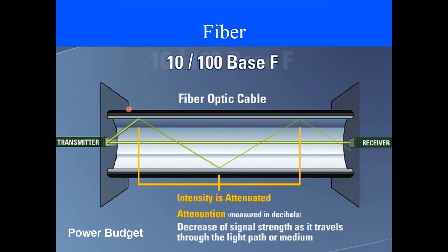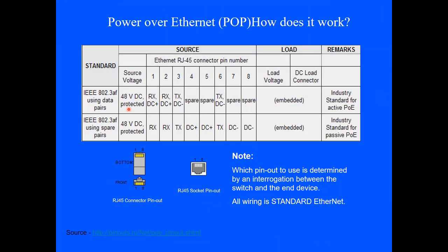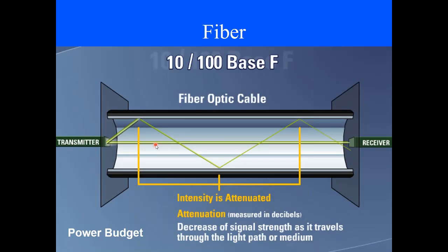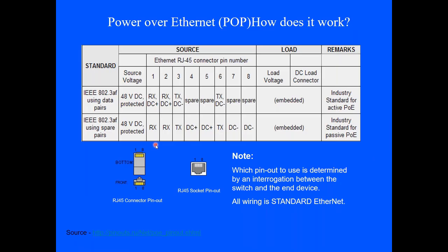So just like we had 25 plus 25, the 6 volt floating, with Ethernet, it uses a 48 volt signal. What's happening now is they've added, since I had these 4 extra wires, I can add 48 volts to 4, 5, 7, and 8. So why does that slide keep changing on me? That's so rude.